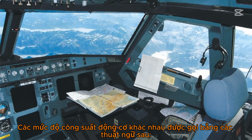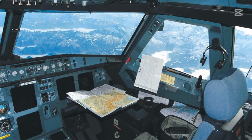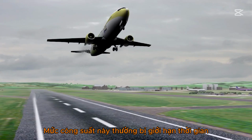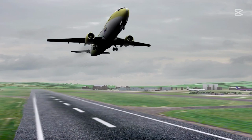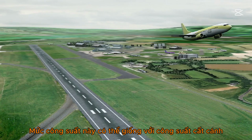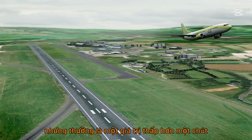The different levels of engine power are nominated by the following terms. Takeoff thrust. Maximum thrust available from the engine. This power setting is normally time-limited. Go-around thrust. This power setting can be the same as that for takeoff thrust, but it's normally a slightly lower value.